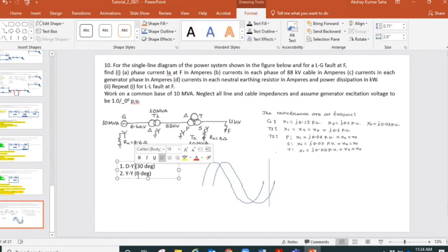Then if we connect these two transformers in parallel, circulating currents will flow between the transformers depending on which voltage is higher at that point in time. Does that make sense now? Yes, sir. But how do you fix that though? What do you do?